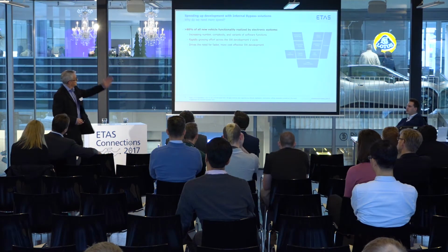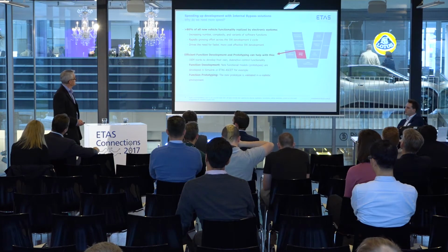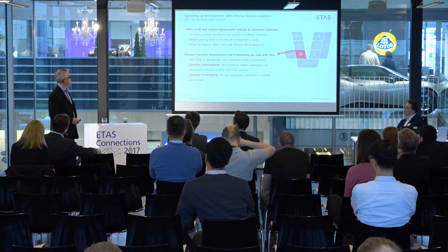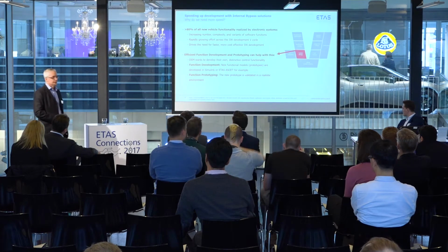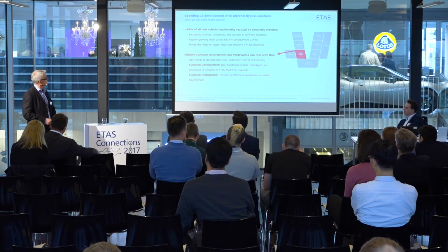So obviously we'd like to increase the efficiency all the way across that V-cycle, but for the purposes of this talk, I want to focus on this bit. So more efficient function development and prototyping. Here the OEM wants to develop their own distinctive control functionality. So they start by using Simulink or maybe ASCET from ETAS to develop their new function. And then they want to do some early validation of that prototype in a realistic environment. And they do function prototyping to do that.